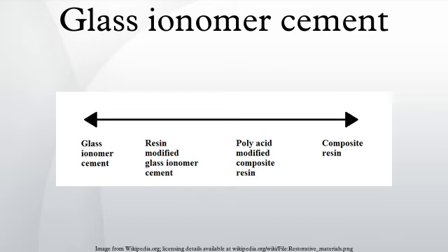Physical strengths. The main limitation of the glass ionomer cements is their relative lack of strength and low resistance to abrasion and wear. Conventional low-viscosity glass ionomer cements have low flexural strength but high modulus of elasticity, and are therefore very brittle and prone to bulk fracture. Some glass cermet cements are arguably stronger than conventional materials but their fracture resistance remains low.